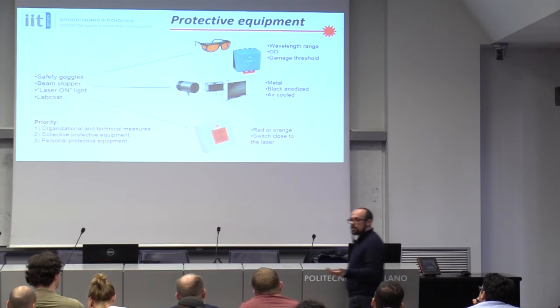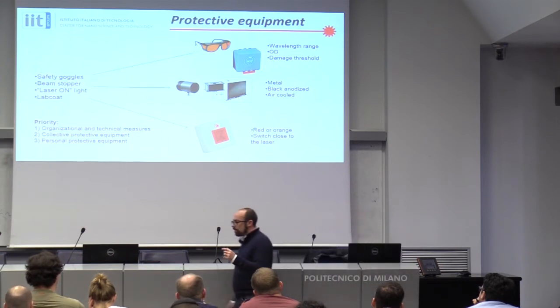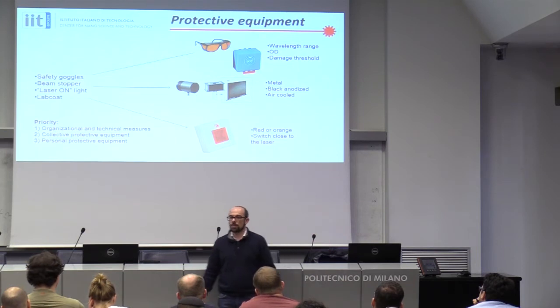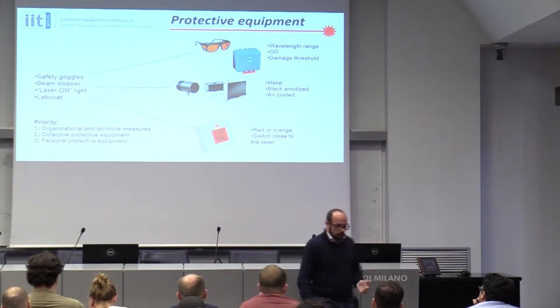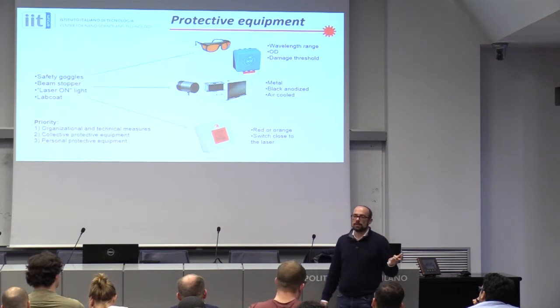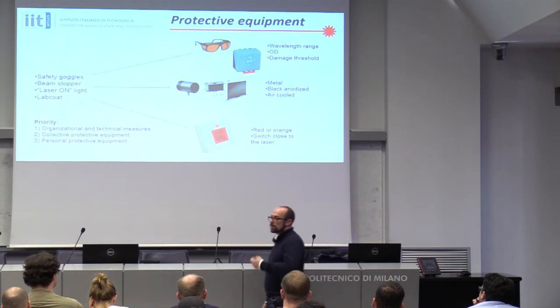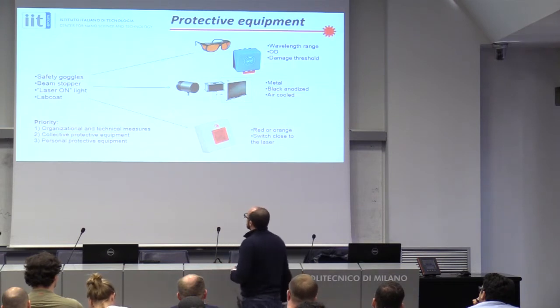That's actually the easiest part. If you put your laser in a big box, and outside the box nothing is coming out, you're pretty okay. You just have to take care that whenever that box is open, the laser is going to stop. It's pretty easy electronics. You just have to have an interlock in that case, right?